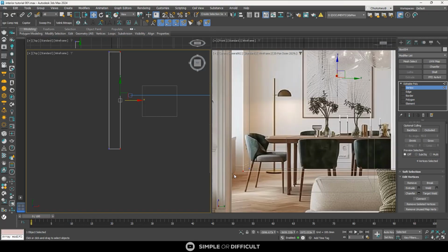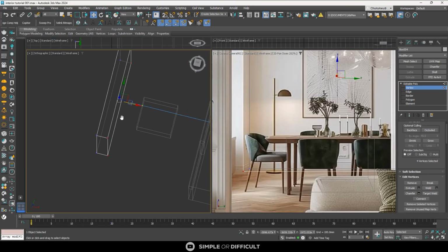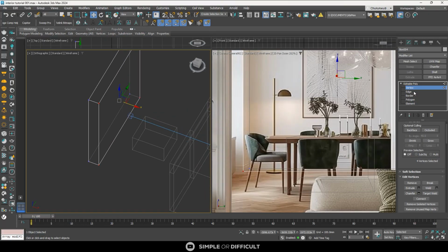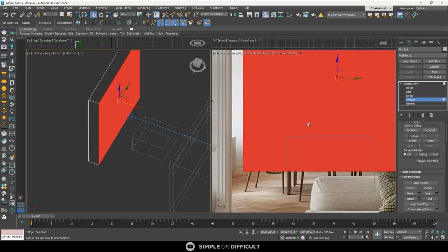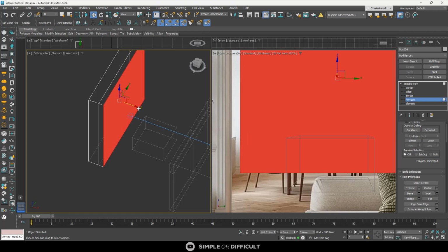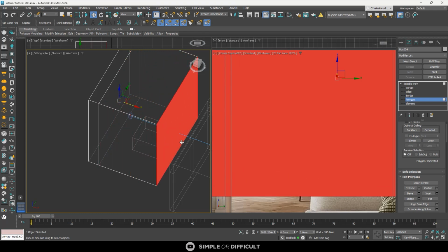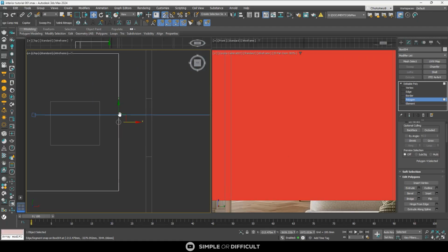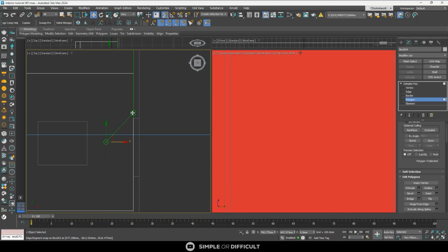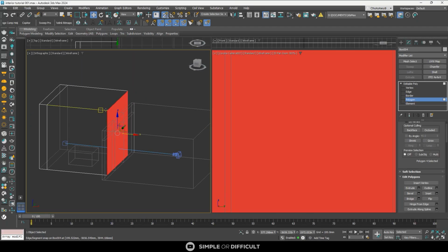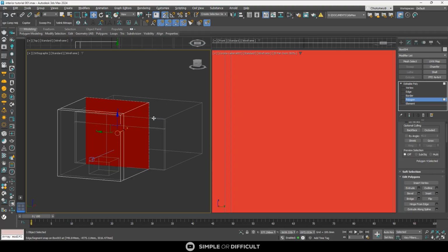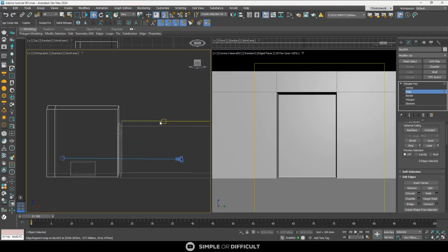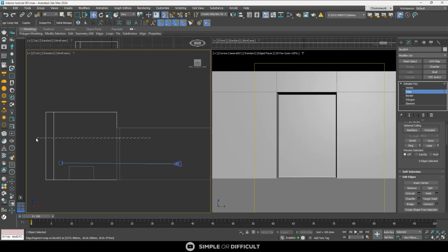So yes. The next thing I want to do is drag it out so I can create another segment from there. So I'll use this polygon selection mode and then drag it out till I meet this. S to turn on the snap toggle, hit that place. So yeah, S selection mode, connect.